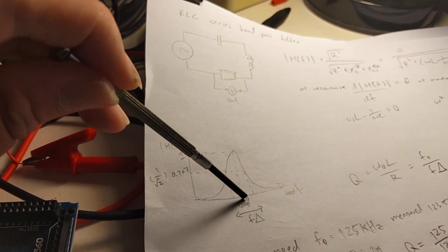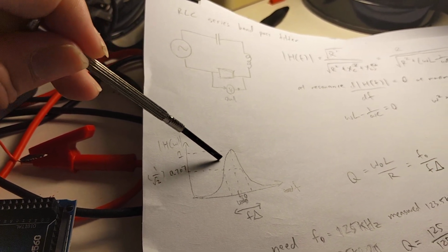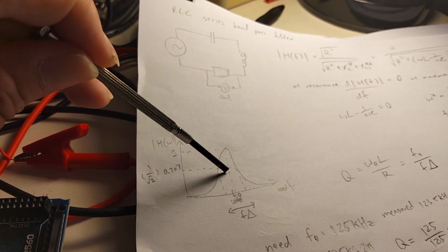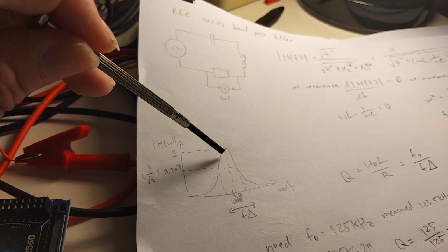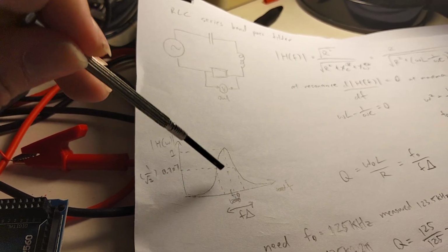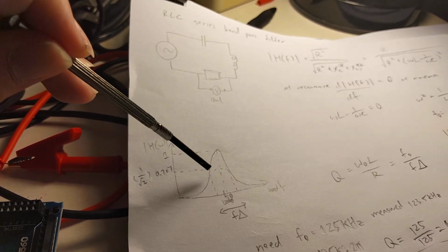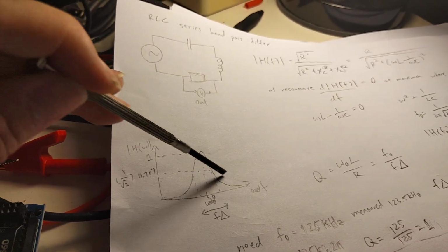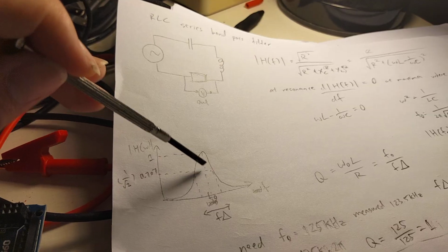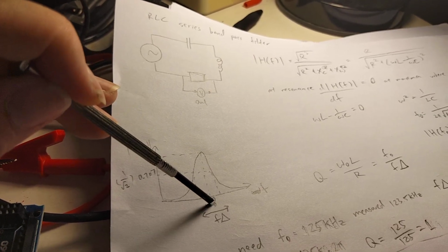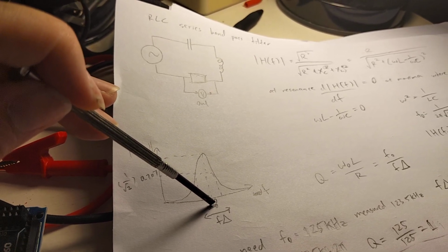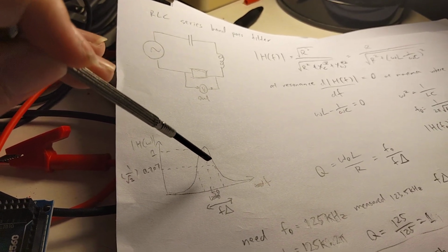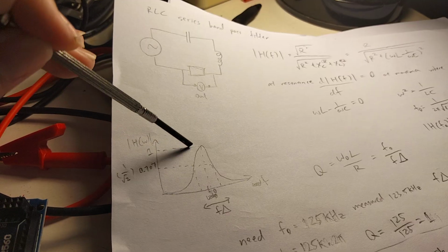There's a resonance frequency that it doesn't block at all, but then to the left and right of the resonant frequency, it's basically going to block more and more of it per decade of frequency. And the Q factor determines how broad this peak is. For example, if we let in a resonant frequency of 10 hertz, with a really high Q factor, it'll only let in 10 hertz. So this peak will be very sharp.